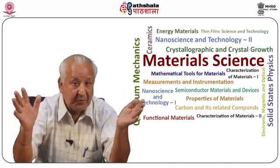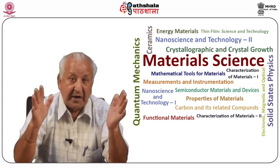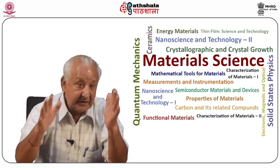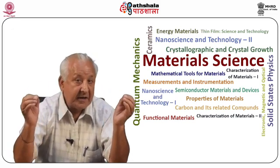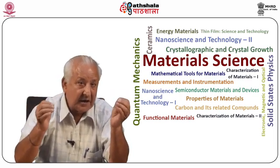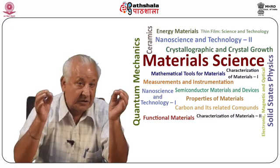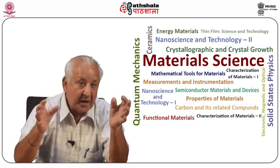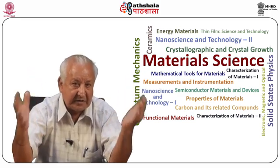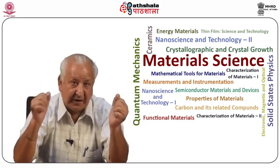In this case, it is important that the material does not have different densities when in the solid and liquid phases. Suppose the solid material has lower density than its melt. The crucible containing the charge is likely to crack. However, if the solid has a greater density than its melt, it will lead to differential dimensions of parts of the growing crystal with respect to the crucible. These are the problems with such materials and can be overcome by some specialized techniques which may, however, take the technique far from being a simple one.